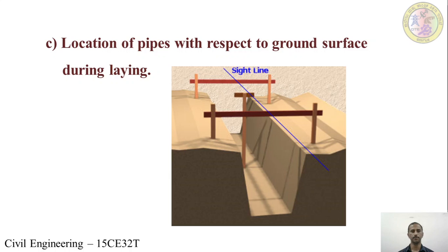If we are to lay the pipe under the ground, a minimum depth of 1 meter is maintained to prevent the pipes from any impact load from the ground to transfer into them. The width of excavation is equal to diameter of pipe plus 300 to 400 mm on either side, so that the laborers can work the pipes and pipe joints. Minimum width of the excavation is 750 mm.